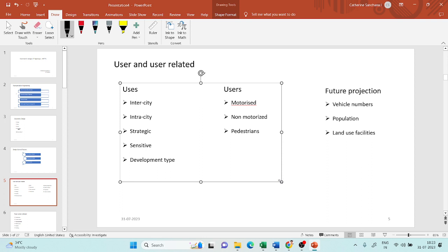So this is use related. What use is of the pavement to you? It is in the border roads, and for the border roads, what are the factors that affect them, the economic factors or the environmental factors, and that should be brought in when you design the pavement. And sensitive, say if you are next to a school zone or a hospital zone, that will also play an important role in the geometric design.